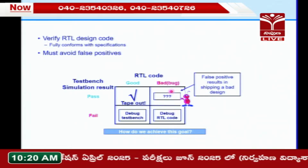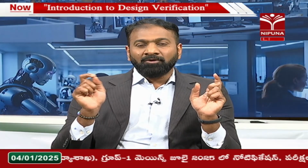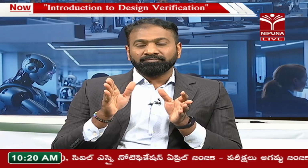Now, in case there is a bug in the RTL, what are we trying to achieve? We want the test bench to fail because we have to debug the RTL bug. An RTL bug means there is an incorrect operation in the RTL which is causing the output to be incorrect for those sets of stimulus or inputs. In such cases, my test bench will be smart enough to capture that failure and report the simulation as failing.